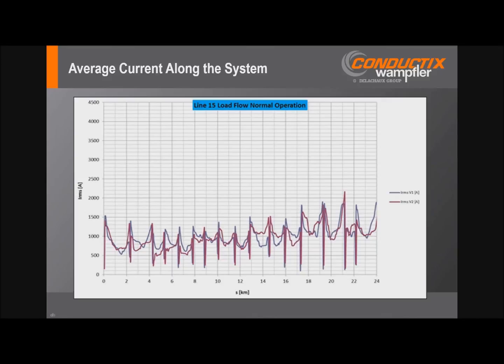Typically, these are approaching speeds of 60, 70 kilometers per hour. It really kind of depends on the size of the conductor, the amount of space, the room that you have. Obviously, the ideal pickup guide would be a very long, gradual transition of geometry to gradually pick that up, but establish good firm contact so we don't have too much electrical erosion.